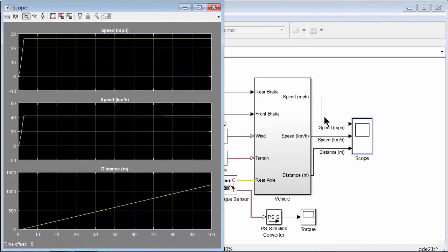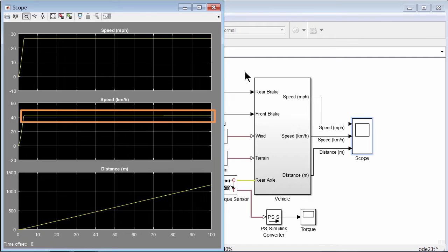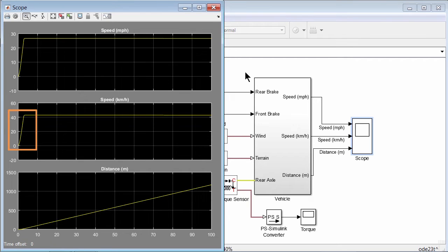Take a look at the vehicle speed here. Because the vehicle is being directly driven by the angular velocity source, it impacts the rear wheel axle. The vehicle speed is therefore proportional to the input angular velocity signal. In this case, since the input angular velocity signal is constant, the output vehicle speed is also constant. We also see a large acceleration during the start. We can analyze the acceleration here in the velocity signal better with the wheel quantity measurements.